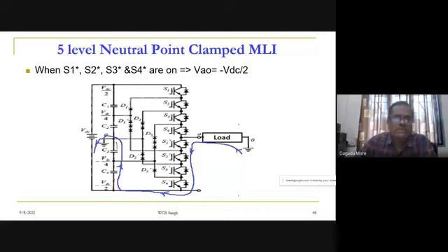The current will be in a downward direction through these capacitors, then through these anti-parallel diodes, and then it will go to the load, and this will again come to point O. So this is our red waveform, we show the negative current and the positive current, and this point A comes to the negative rail.